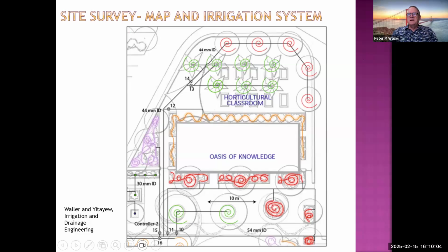If the site was designed by a landscape architect, then you can start with their PDF drawing of the property. And this was an irrigation design that I worked on for a park in Aqaba, Jordan. I just overlaid the irrigation system over the landscape architect's system. And you can see I used my coiled inline drip around the trees.